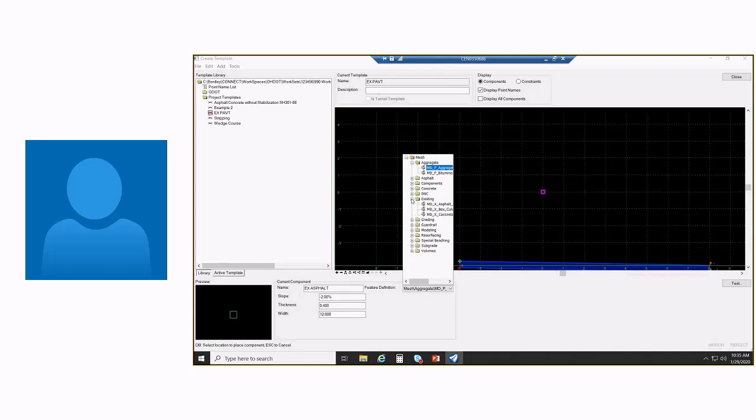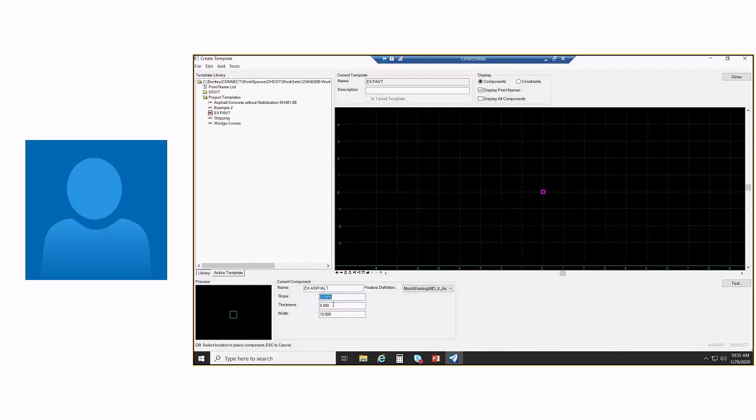We have a couple feature definitions for some existing things, and we probably need to add some more. So again, as you start working through this, let us know what you need. I've got a concrete pavement and an asphalt pavement item. The slope doesn't matter. Maybe there's 3 inches of asphalt out there, and the width doesn't matter either, because it's going to apply it to a terrain.